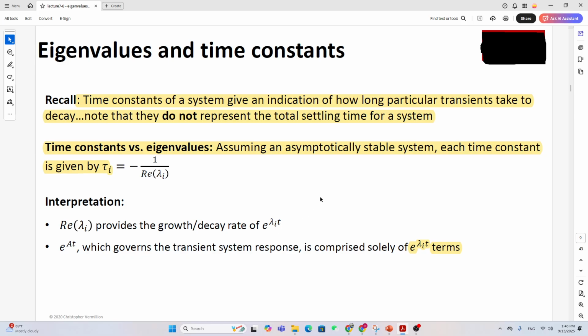Now let's look at what information we can get by looking at the eigenvalue, right? The eigenvalue tells you not only the system stability. As we just mentioned, larger than 0 means your system is unstable. Smaller than or equal to 0 means you have a Lyapunov stable system, which is internally stable.